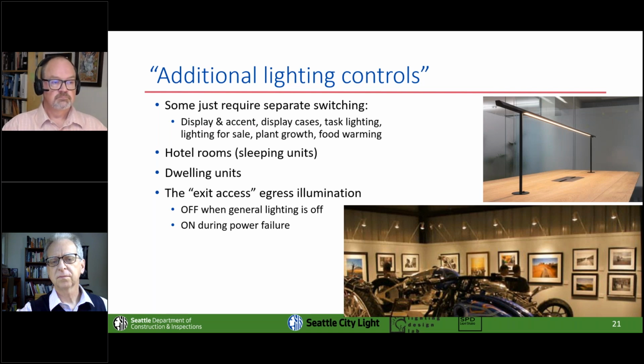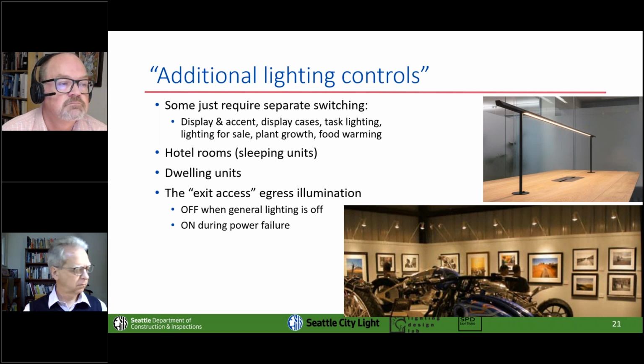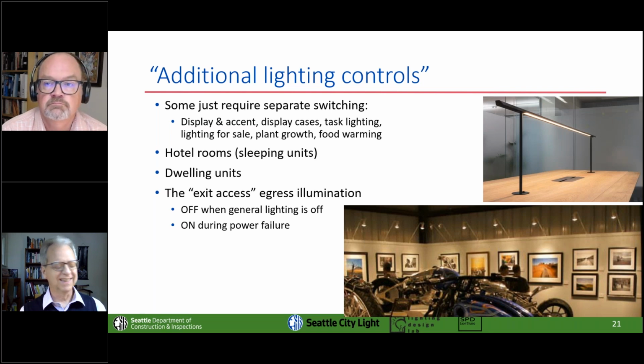Okay, and then Jose had a question on sensors and controls in the code. He said, in reference to C405.2.1 and C405.2.2, does the code verbiage allow us to provide time switch in lieu of occupant sensor controls if rooms are required to have occupant sensor controls per C405.2? No. Okay, got it. When it says you've got to have occupancy sensors, you do, and then everything that doesn't have to have occupancy sensors typically has to be on a time clock control.